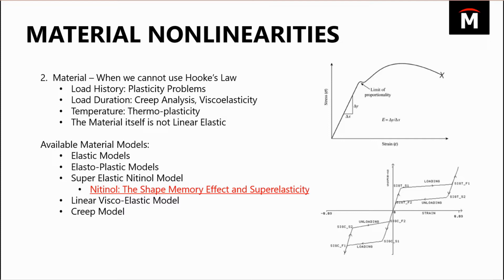Now that's in the material model itself, but the first place I look is, would we have a different response based on how we're loading things? For instance, if you hold a load onto something for a very long time, does it start to get creep or viscoelasticity? That type of behavior from holding something a long time, or maybe something even work hardens and gives you a difference there. Or thermoplasticity, if things soften and change and get more strain as they start to heat up. Now, some materials behave this way on their own.